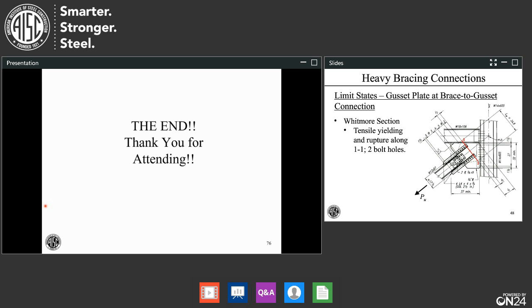First would be to pretend like the plate goes all the way up there, although we know there's beam there, because the beam is going to be in the region with the fillet, so there's a lot of steel there. So I think it's conservative just to use the gusset. You've got to use some judgment. There could be some weird case where that's not conservative, but I'm typically going to just pretend like the plate goes on up there.